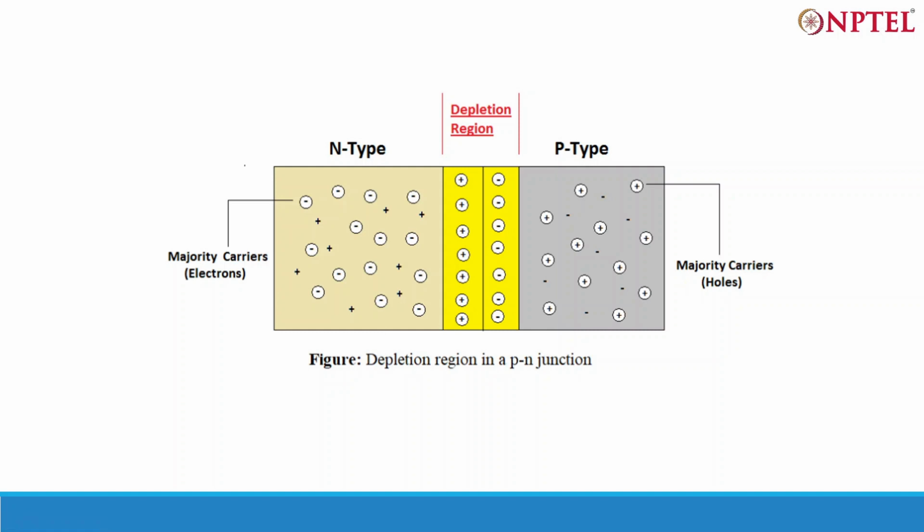This represents a semiconductor. This is the n-type doping, where the majority carriers are electrons, and this is the p-type. This is where electron-hole recombination happens, and this is called the depletion layer. Here the majority carriers are holes, that are positive charges, and on the other side the majority carriers are electrons. So this is how a solar cell is designed. This is the basic function of a semiconductor that goes into the solar cell, the photovoltaic cell.